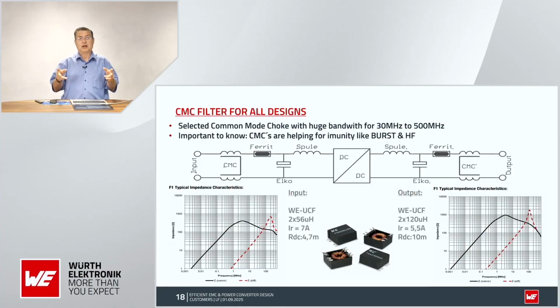This common mode choke cuts the antennas. This is only for the radiated emission. We could avoid the second common mode choke if we put it in the box together with the logic board. Maybe we will not need it. Who knows? We will put it there, and by the measurement we will find out whether we need it or not.